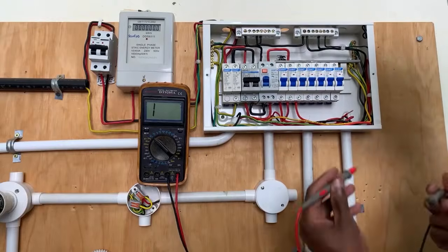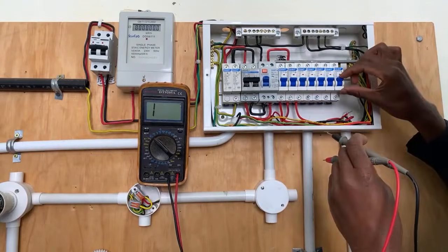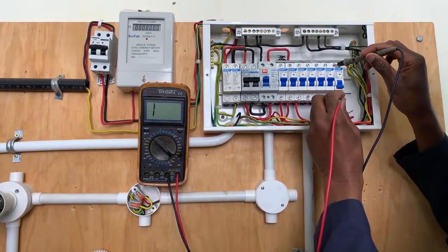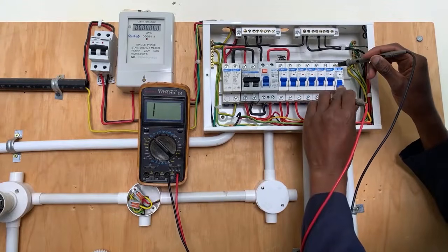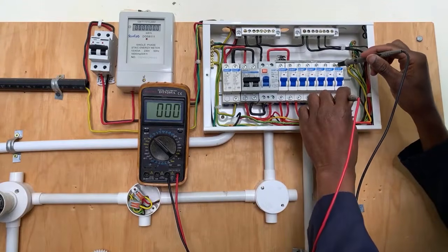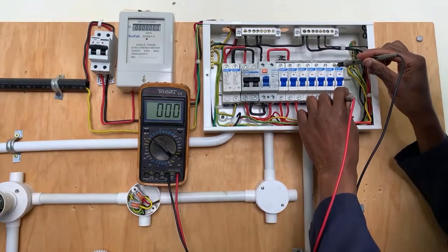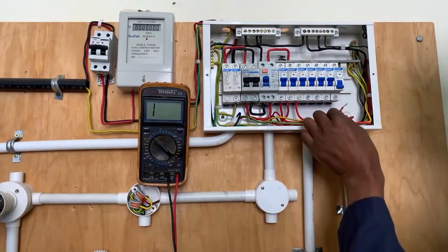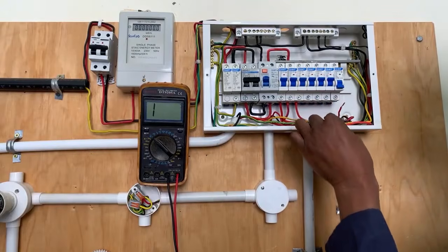Now, what we need to do is to determine whether, see, if you shut it off, you place the probes, you get a 1, infinity. If you turn it back on, there is a short circuit, meaning continuity. But we shall not reconnect this circuit back until we solve the problem.